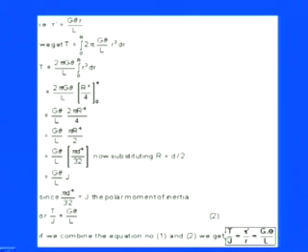Here you see the final relations which we started from the beginning: if we have a solid circular shaft which has a uniform cross section, with homogeneous material properties, under elastic loading or elastic deformation, then whatever the angle of twist or shear strain is coming, it has to be uniform. And it doesn't have different cross sections throughout the length.